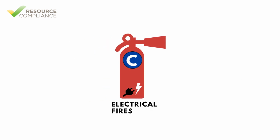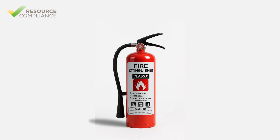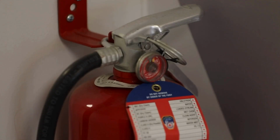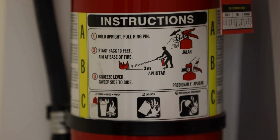Electrical fires are Class C. Carbon dioxide and dry chemical are both effective at extinguishing Class C fires. Class C extinguishers can be identified by their blue circle with a C inside. Because dry chemical extinguishers are effective in stopping Class A, B, and C fires, they are commonly found in many workplaces and are identified by an ABC designation on the unit.